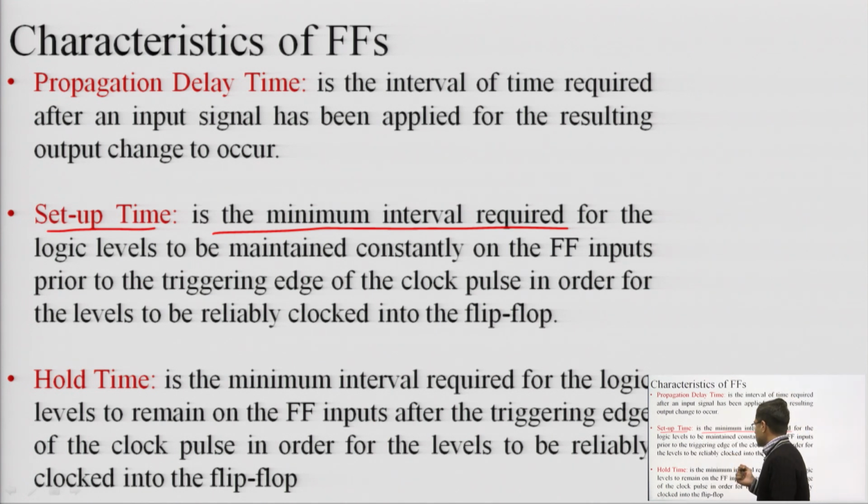Okay. So, this is the setup time. That means for that amount of time the input has to be there, so that whenever the clock edge arrives, it will be triggered inside the flip flop, it will be fed inside the flip flop. So, this is the setup time.